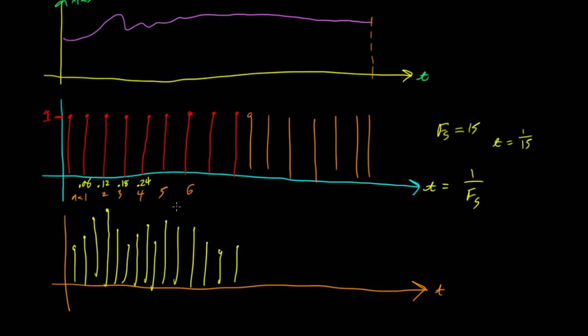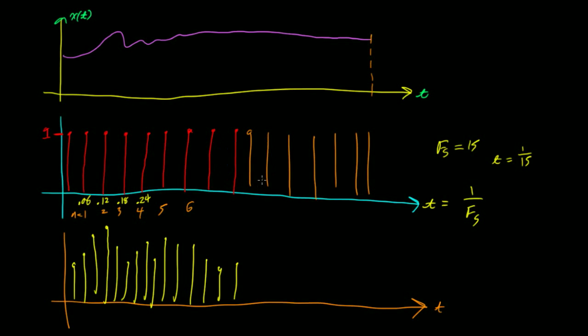So our goal for today is to look at aliasing both from a time perspective and also from a frequency perspective, if we have time. We'll see. Okay. So the plot on the lower axis is what we get when we multiply our impulse train that has impulses every 0.06 seconds by our input signal. These are the samples that we get out from that, which correspond to the yellow points in the top graph. Does that make sense?